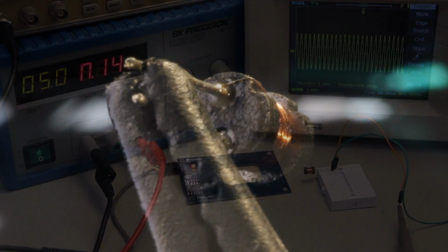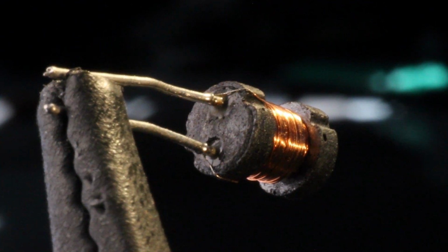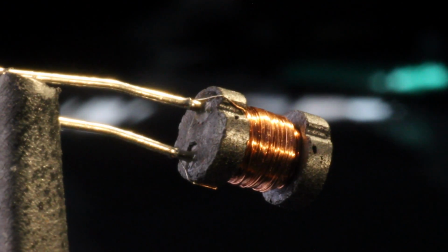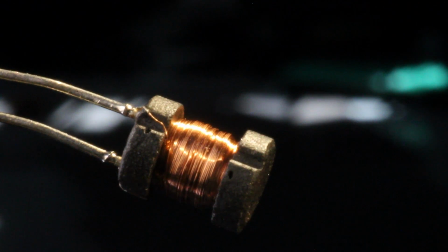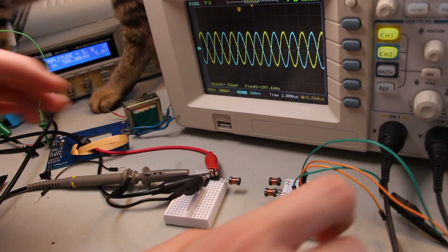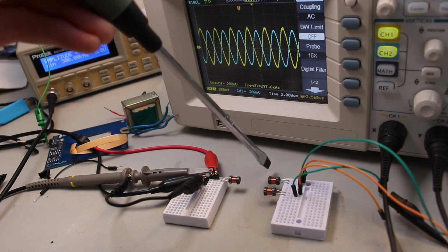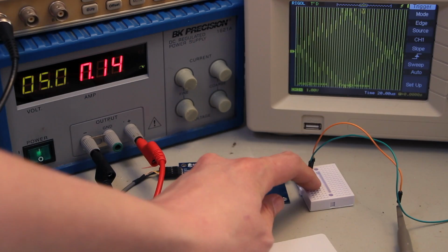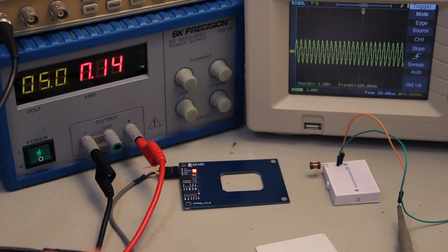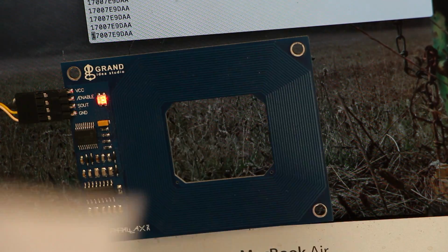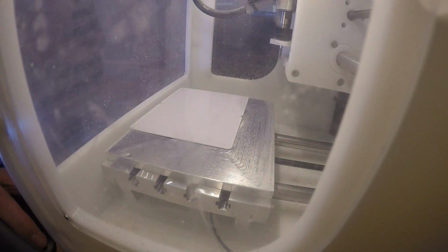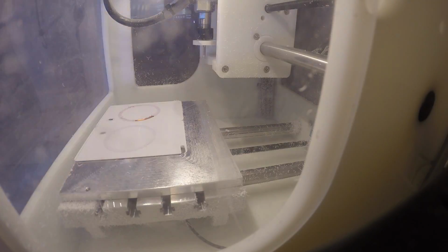This is a coil with an inductance of 10 millihenries. Normally you might see a coil like this providing temporary energy storage in a small boost converter. But here we'll be using it to transmit and receive signals made from changing magnetic fields. This is how many RFID cards work, especially older door access control cards. The RFID reader has a coil made from traces on its circuit board, and the card has a coil made from very fine wires embedded in the plastic.